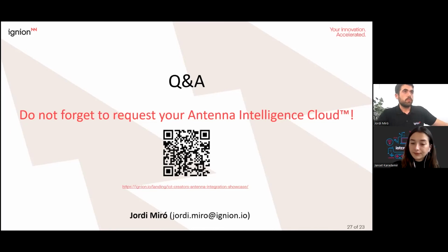But if you need to put a screw, let's say, very near the antenna, I would recommend, for example, a plastic screw. I saw a lot of that in designs, in matching network services with other customer devices. But if you mandatorily need to put a metallic screw near the antenna, we can evaluate the performance in our lab, and most likely the antenna will perform okay, but it is only a recommendation.